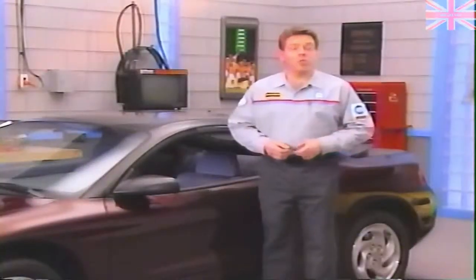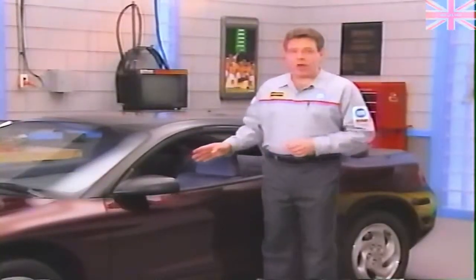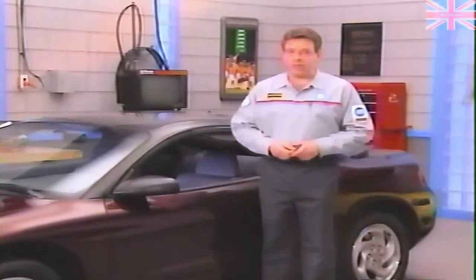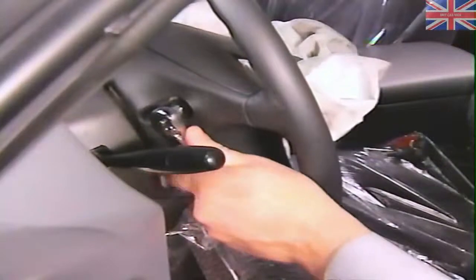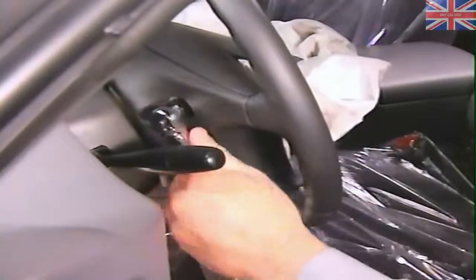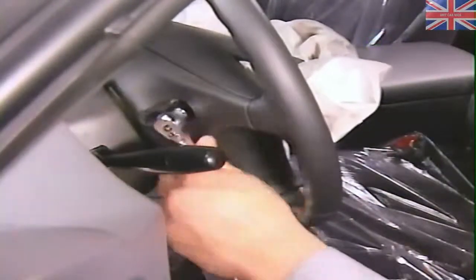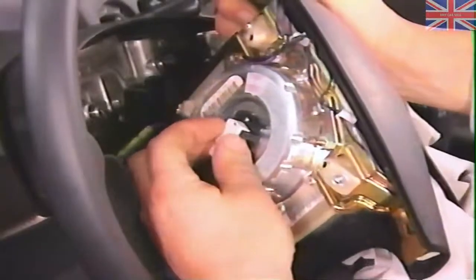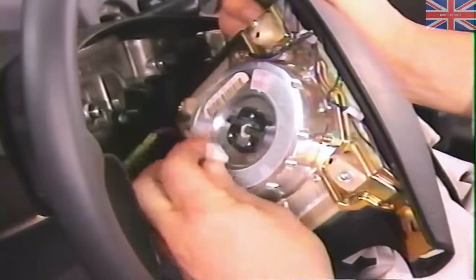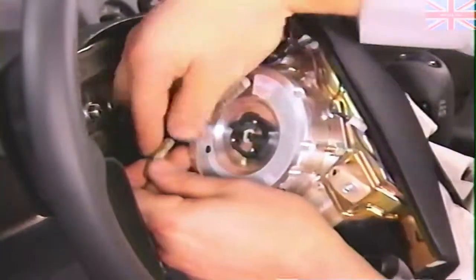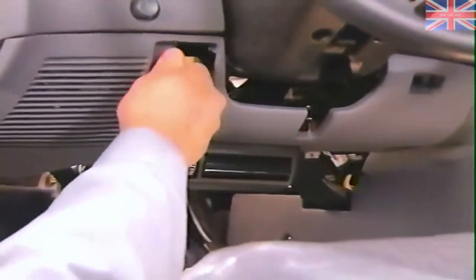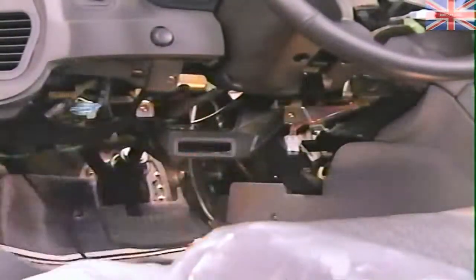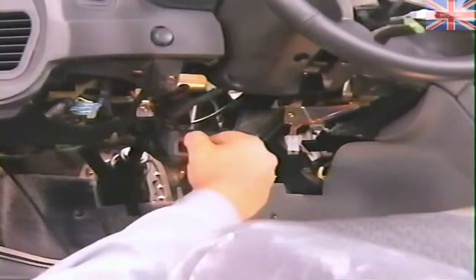The next step is to remove and replace the driver airbag, clock spring, steering column, and intermediate shaft. Start by removing the 4 bolts that hold the driver airbag in place. Lift the airbag from the steering wheel and disconnect the airbag connector and the horn connector. Remove the ventilation ducts using the procedure provided in Section 24 of the service manual under ventilators.